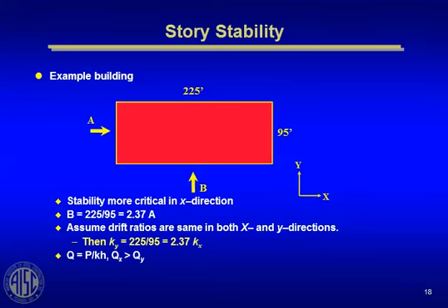Now, to take an example here, look at this rectangular building, and I'm going to tell you a famous building that had this very problem. This building has obviously a big wind sail in the B direction or the Y direction, right? And yet it's very narrow in the X direction because the wind sail area A compared to wind sail B, A is much smaller.